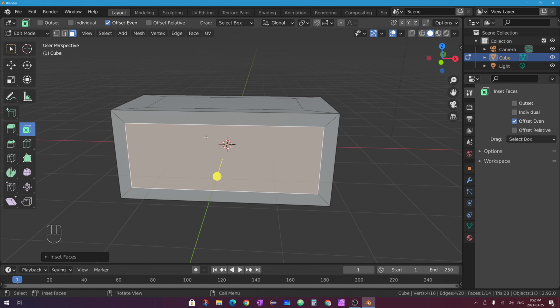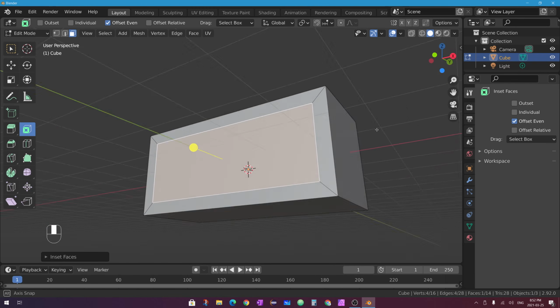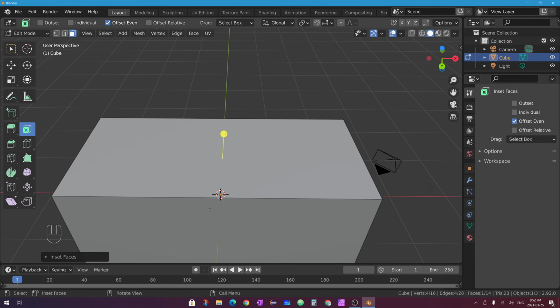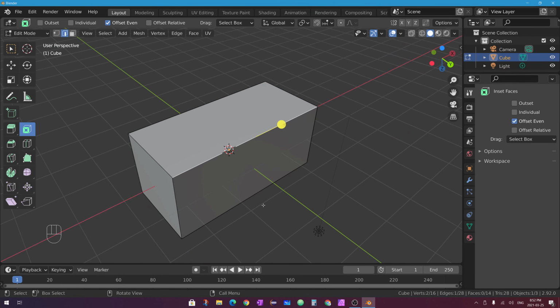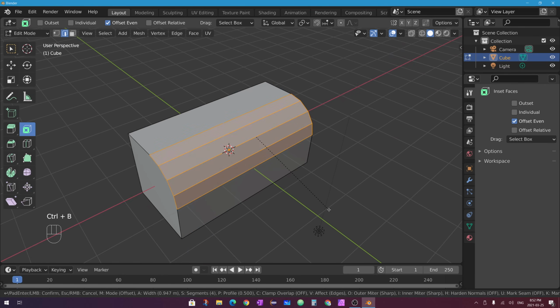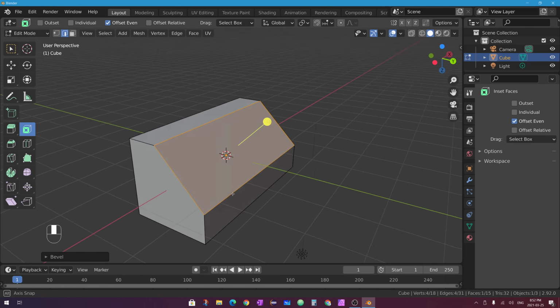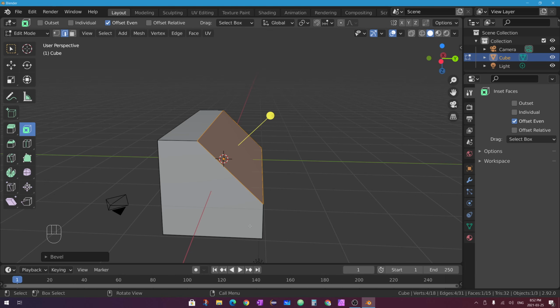This problem with the scale being stretched, not 1, 1, 1, will also affect you if you're trying to bevel. If I grab, let's say this edge on the bottom and I bevel it, Control B, you can see if I scroll down just one face that it's beveling at a nice 45-degree angle.